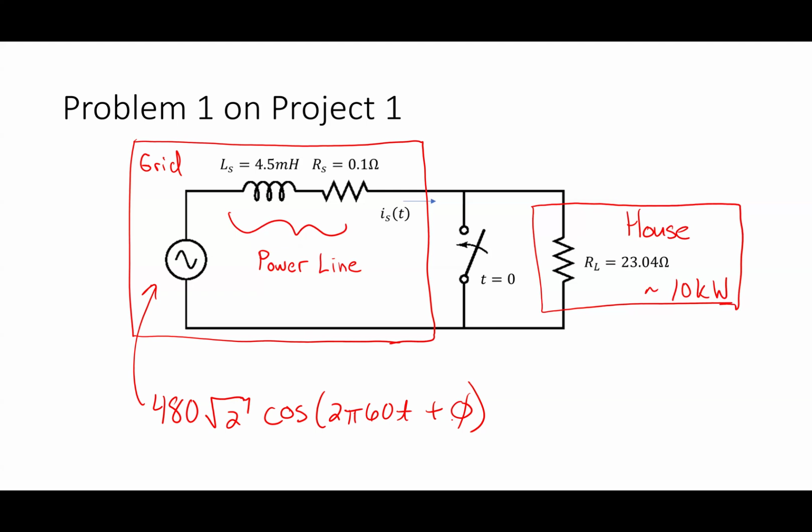Let's go through. What theorems did you learn in Circuits 1? KVL. KVL, that's good. KVL is one of the most important. KVL, KCL, Ohm's law. What? Exactly. Thevenin's theorem. Thevenin's theorem says I can take something that's endlessly complicated, like the electric grid, and reduce it to a voltage source in series with a resistance. Or more generally, I know not all of you are there yet, a voltage source in series with what we call an impedance.